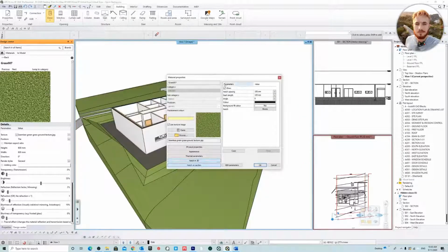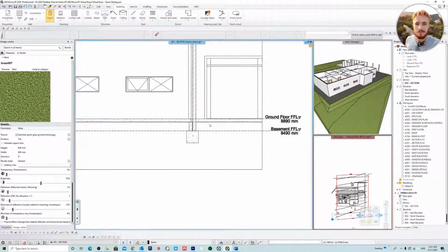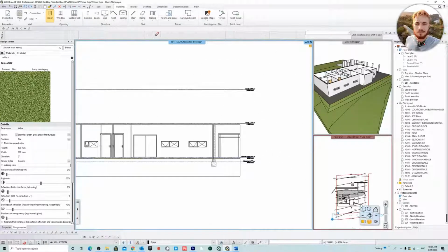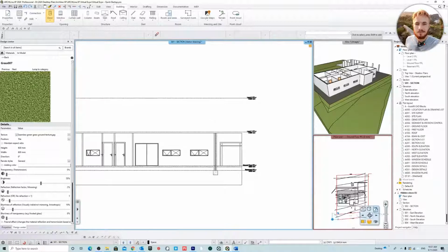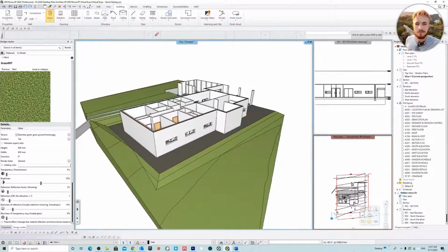In the section properties, you can either change the types of hatches, but for the moment I'm going to just switch these off because we don't necessarily need to see that for our sections at the moment. And I'm just going to hit rebuild. Now if you go to your section, you can see there's a nice clean section view that you can use for your documentation. And for this, I'm just going to switch it to hidden line removal. So that quite covers it.